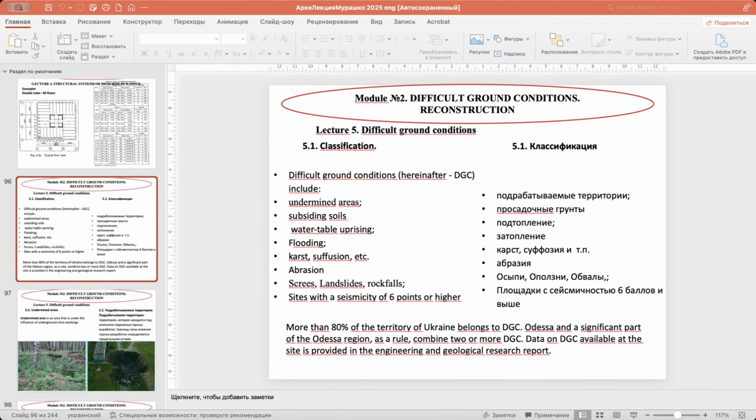with reinforced concrete elements. Yes, there are possible variants like a base isolation system, which can reduce the impact of seismic earthquakes. But nevertheless, some difficult ground conditions will make your building stiffer, or you will have to make a bigger number of walls or something like that.